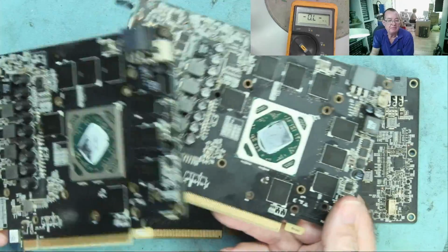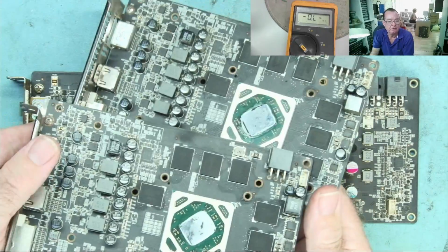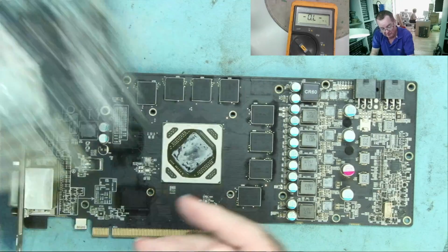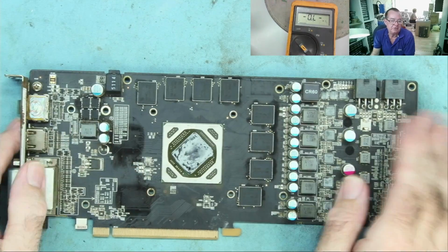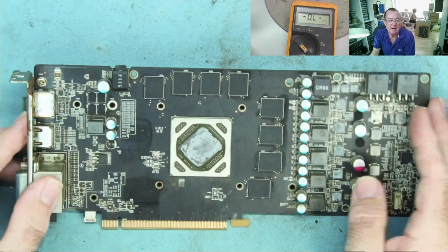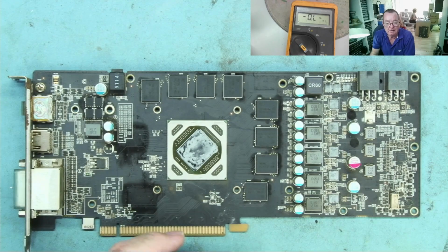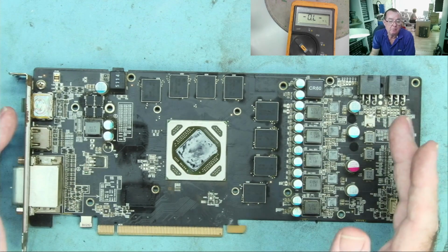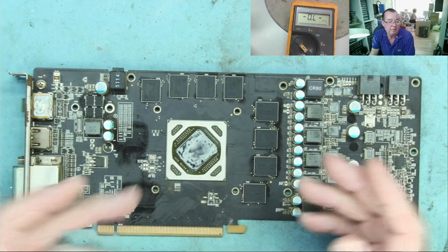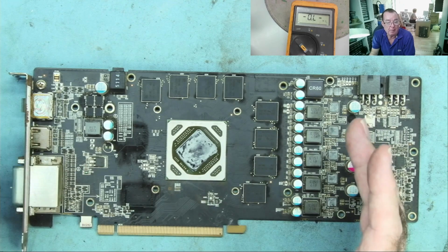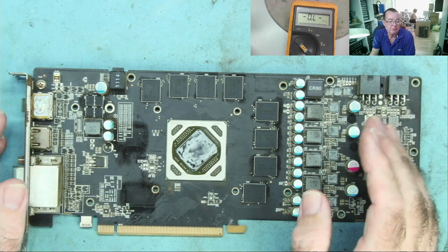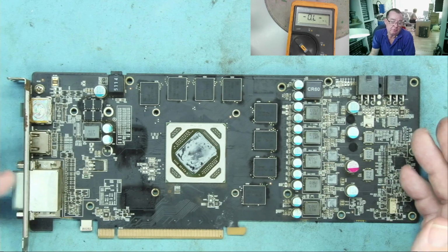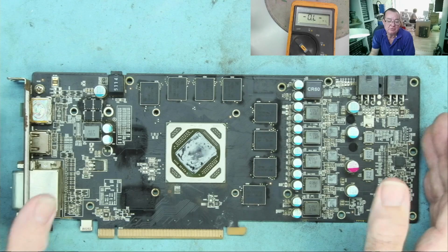So there's a possibility we have one or both faulty GPUs here, but it's just a possibility. And this one, I don't see anything obvious, but I don't have one to compare with, but I don't see anything wrong. So the next thing then, guys, is we're going to power these cards up next and have a look to see what voltages we can see. That will determine definitely which voltage rail is which. And if any voltages are missing, we'll know straight away we have a problem in that part of the circuitry.